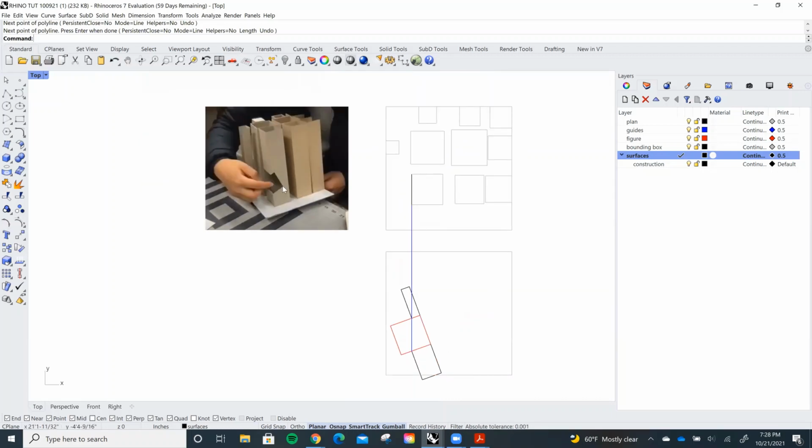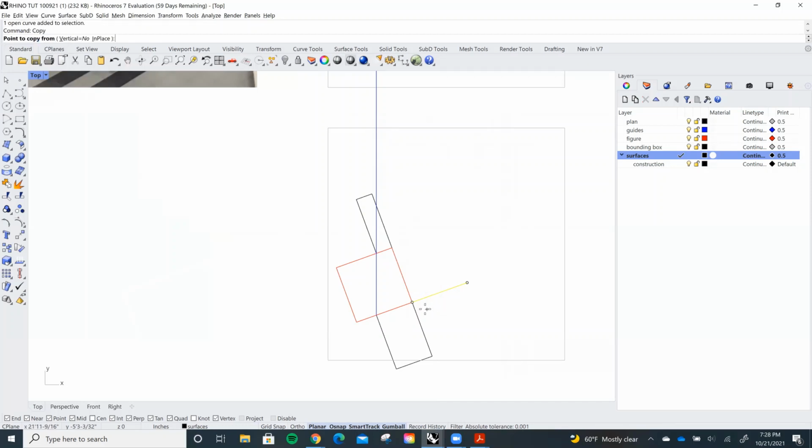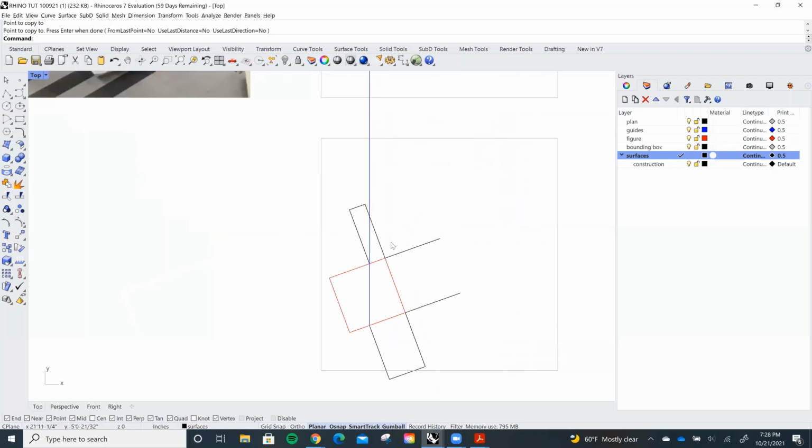And in building this side piece, you want to do essentially the same too, right? So if you imagine this, right, as the front of this unrolled surface, this side will be on here, right? And so if it has the same depth on all these edges, I can just copy this by holding down Alt and then rotating this 90 degrees and then moving this towards the corner of the square again, right? And then because I know that it's the same depth all the way through, I'm going to simply copy to the other corner too, and then cap this, right?